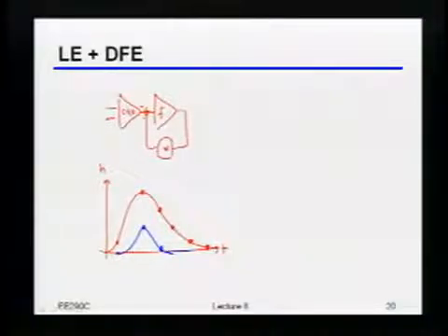Right? Well, okay, so now if I have even just a one-tap DFE, how should I readjust my continuous time linear equalizer? What do I want it to do now? Leave the first post cursor alone. Yeah, I just want it to leave the first post cursor alone, right? Why is that actually good? How does that help me? It improves the amount of swing you have available to transmit. Yeah, exactly. Basically, I'm doing less equalization, so the amount of DC gain that I'm throwing away is smaller, right?